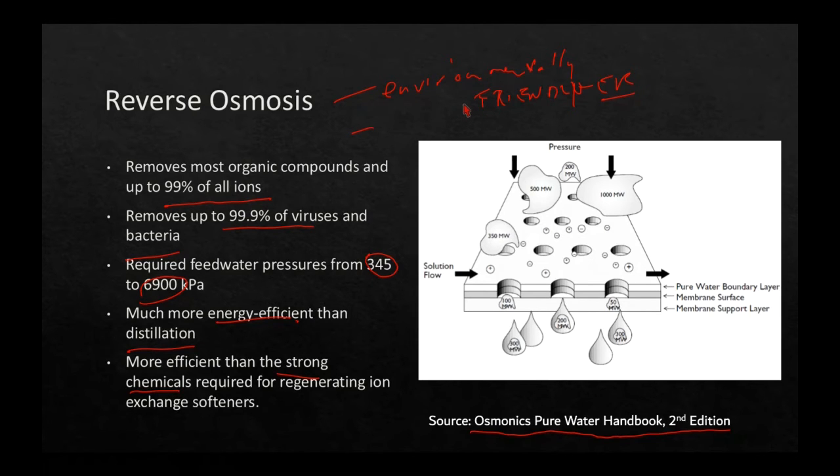There's a fairly big initial cost in a very large RO system. Let's say too that these systems are good for final polishing. Just like the demineralizer, we don't want to take really hard water and whack it through the demineralizer. We're going to use a lot of chemicals and get a lot of premature fouling of resin.